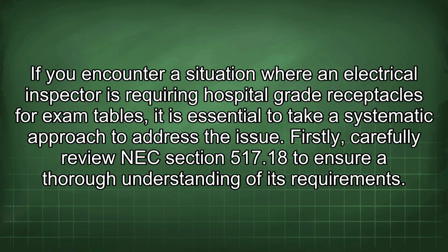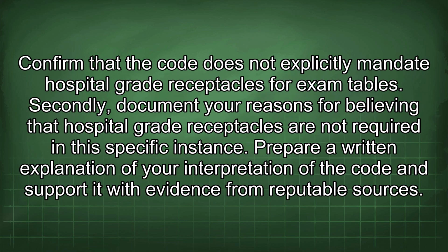If you encounter a situation where an electrical inspector is requiring hospital-grade receptacles for exam tables, it is essential to take a systematic approach to address the issue. Firstly, carefully review NEC section 517.18 to ensure a thorough understanding of its requirements. Confirm that the code does not explicitly mandate hospital-grade receptacles for exam tables.